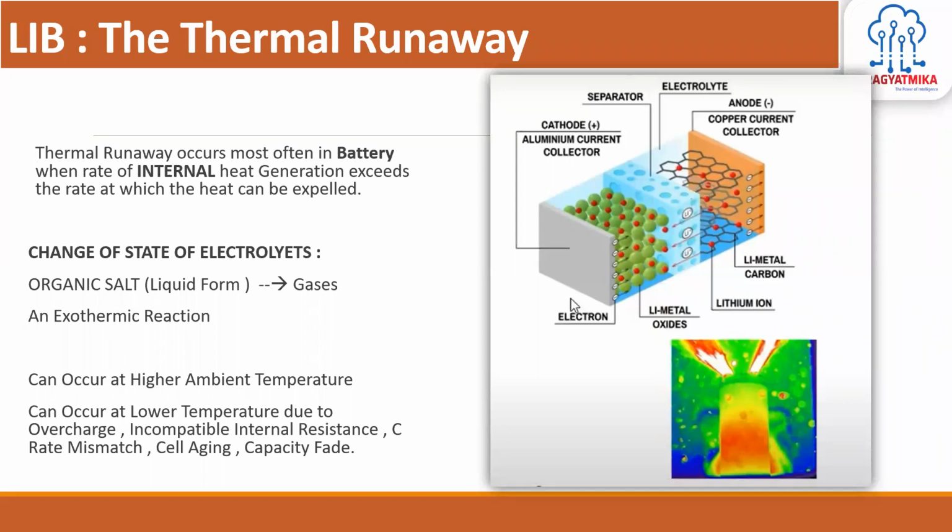As I have shown you in that video, there are the two sides of the cell which we had cut, and the terminal on the cell is used as the cap, for the excess gas which is getting emitted during the reaction, whether you are charging or discharging. Through that vent, the gas will get emitted out. But if the rate of production of the gas is higher than the rate of emission, that cap will definitely burst out, and that happens in the case of a lithium-ion thermal runaway process.